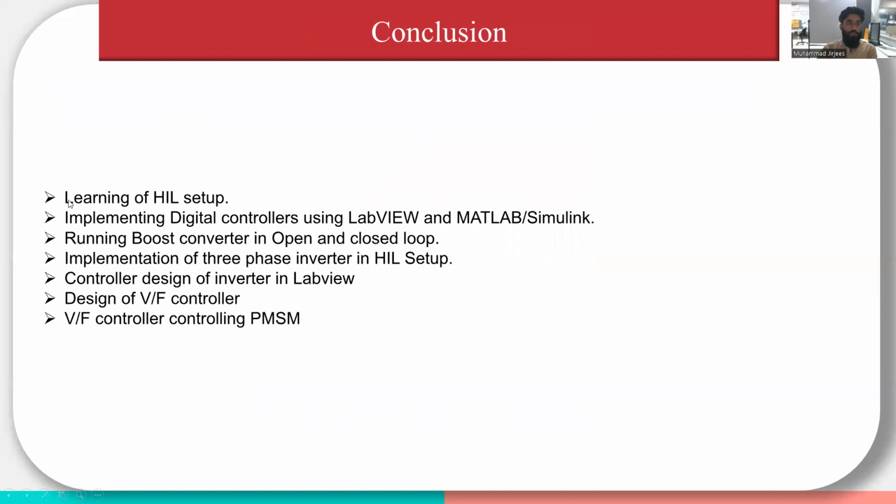Now let's move toward the conclusion. Basically, starting from the first step, that was learning the HIL setup. Then we implemented our digital controller using LabVIEW and MATLAB both. Then we ran our boost converter in open and closed loop successfully. Then we implemented the three-phase inverter in the HIL setup. Then we designed our controller for the inverter in LabVIEW. Then the design of the V/F controller, and controlling our PMSM with the same V/F controller, was achieved.